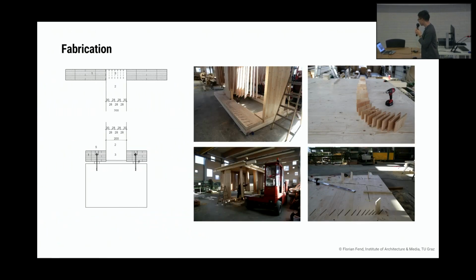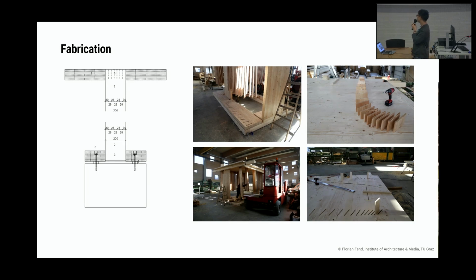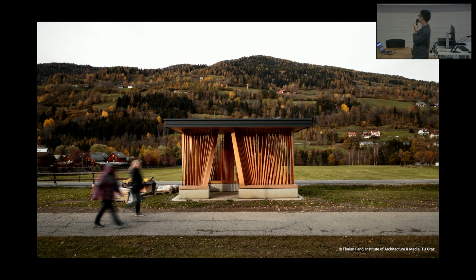The fabrication process, as I mentioned already at the start, is basically you have these slotted holes where these timber elements are slid at the top first, and then twisted and slid into the bottom. This was a system that the students actually developed, and the fabricator at the end also used a very similar method to build it. Each of the units was totally prefabricated off-site in either single, double or half units, and then brought onto site and screwed onto the concrete bases. Here's another one of these typologies where you see this timber element which sits on top of this concrete base, and the concrete bases were poured on site, so it formed a seating element for this structure as well.